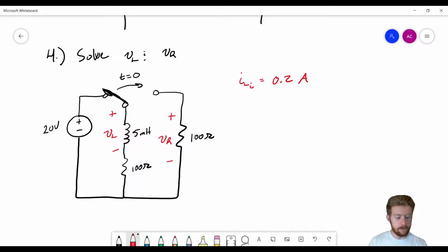Okay, so that inductor is going to supply that same current to a 100 ohm resistor as well as the other 100 ohm resistor in order to close that circuit. So that's the only way that that inductor is going to be able to keep its current flowing. In this polarity, we know that the inductor is going to try supplying current downward. And in order to do that, it actually has to have a negative voltage, because of the way we drew this.